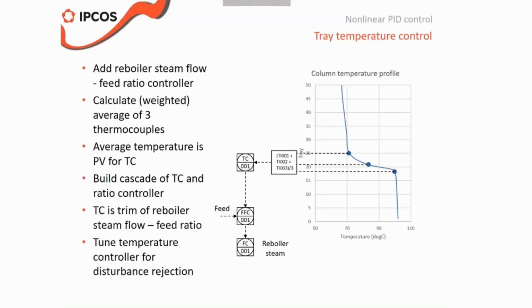Okay. One other question regarding pH control. Suppose you have a buffer in pH control which shifts from run to run and therefore the response also depends on the flow. Is a characterization block still the right solution or are there other tricks available?